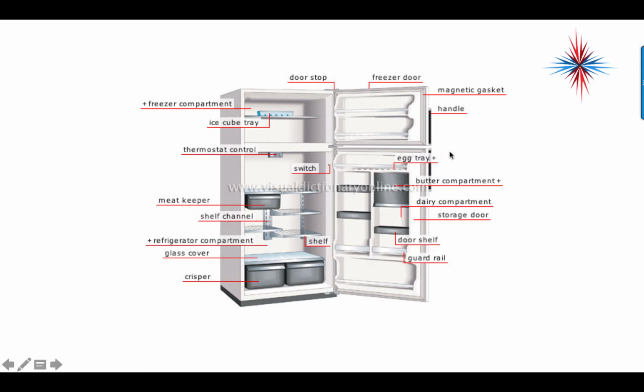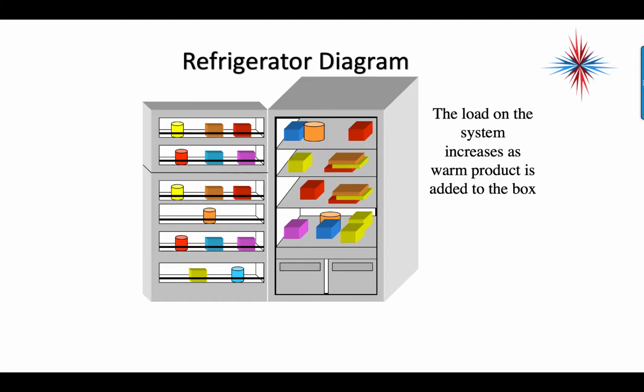Very specifically, we have to keep an eye on the gaskets all the way around. We have to keep an eye on the ice buildup in the freezer compartment because, believe it or not, in most refrigerators, unless you get into the newer higher end models, the freezer compartment is what supplies the cold air down into the refrigeration compartment. There's a fan that blows back and forth.